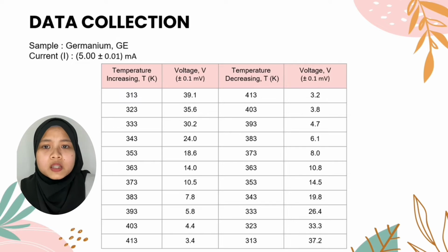While decreasing temperature, the same way applies, but this time we turn off the heat and take the voltage from the highest temperature to the lowest. There are 22 voltage data measured in total, varying with the temperature that we obtained in these experiments. The resistivity of the sample can be calculated from the temperature of the oven and the voltage.